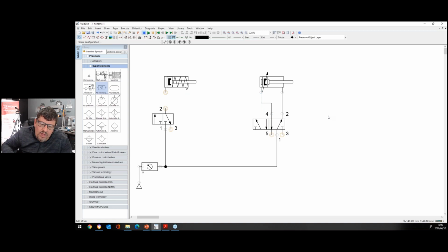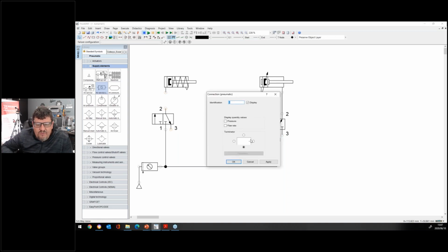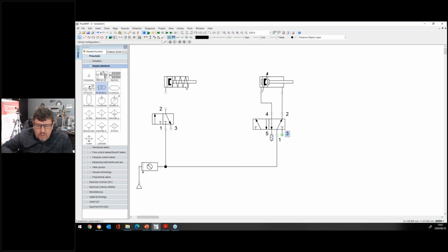All right, that means the moment when your air supply is switched on, the air will flow through from port number 1 to port number 2, and it will send my cylinder into the rear position. Right, and then if they actually wanted to extend, now I also want you to understand this, on port number 5 and port number 3, we need to connect. For example, in an environment where there's a lot of noise, we need to put silencers there. Right, I'm going to put a silencer on both the outlet ports. That is my exhaust ports.